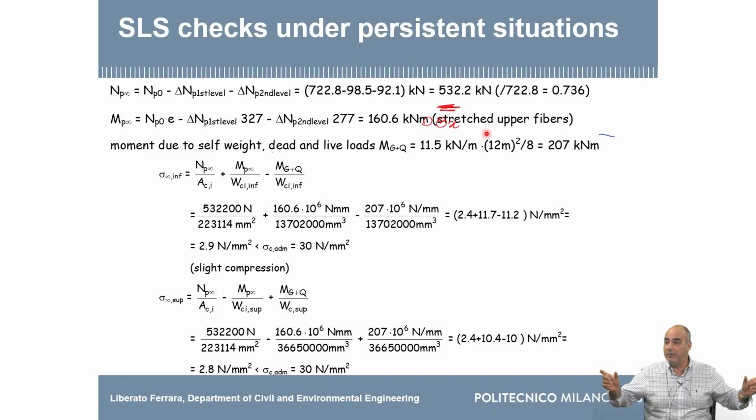It creeps, but we will see in the connections, you have seen also yesterday, never just put the element there and leave it to stay just because of self-weight and friction. You always have some pins or some steel profiles that keep it fixed. If the element creeps, it tends to rotate, it tends to sag a little bit. If these connections tend to oppose this deformation, tend to restrain these deformations, then you will have parasitic stresses. So this is important to bear in mind.